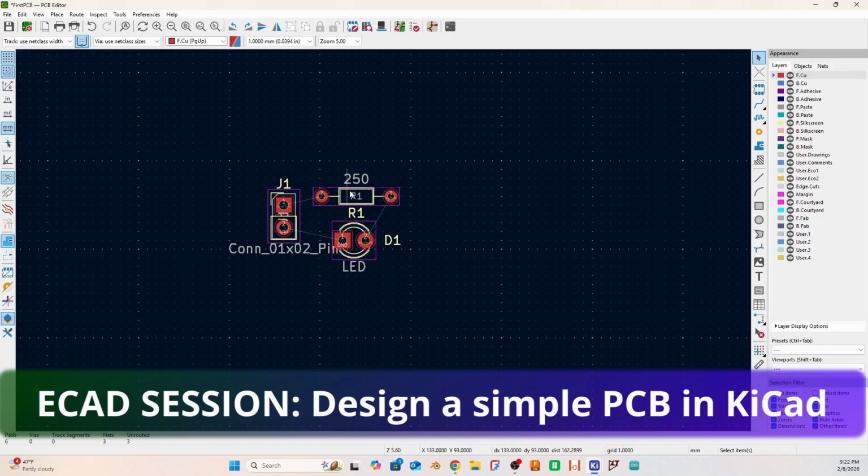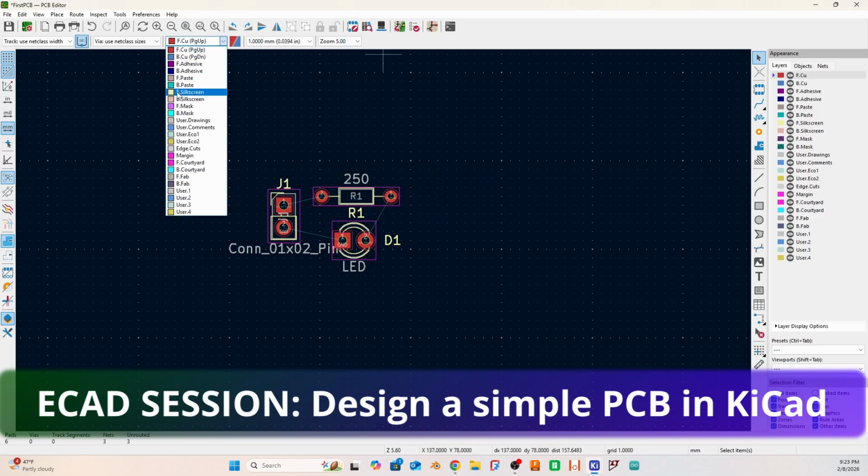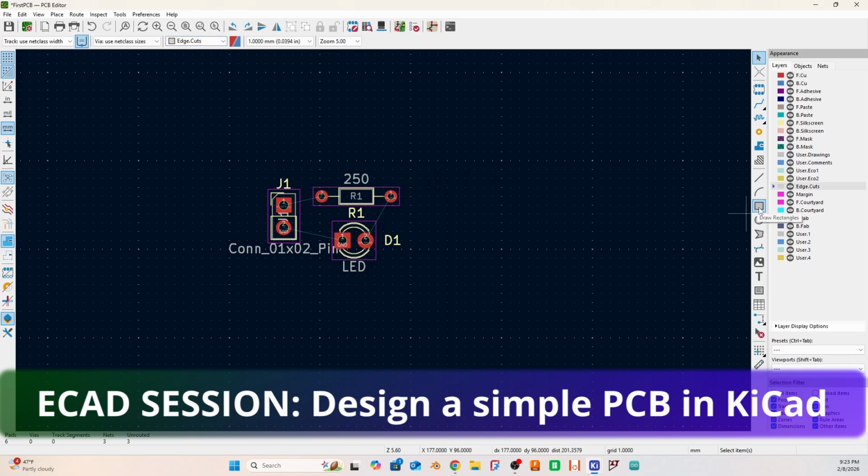Alright, now we have a PCB layout. The layout is pretty good to me. What we want to do is set the border for the PCB. So we want to click on edge cuts somewhere here. You can just select edge cuts here, or come over here and select it. Okay, edge cuts. Then we're going to grab this and make a circle in here. Essentially we're going to give the shape of our PCB. So let's go about that. Perfect to me. That's great.